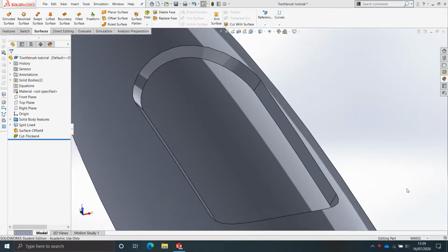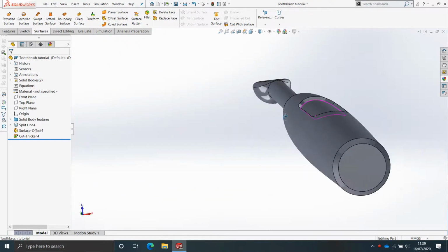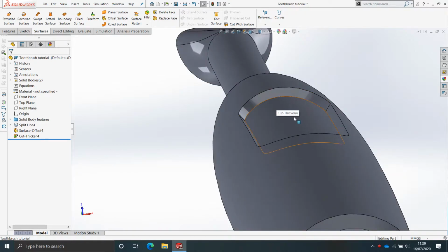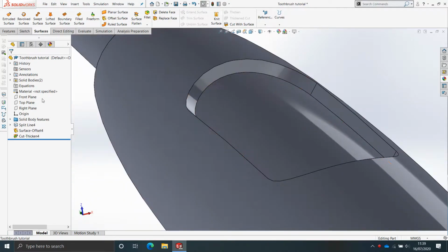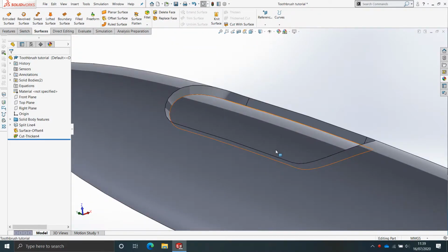So, now that we have the recess slot geometry, we can think about adding a button that will sit in this slot and that will match the curvature of this front face. And whilst we want to add a button in here, we want it to be a separate part, or a separate body in this part file, should I say. In order to do that, it's actually pretty simple, and we can just use the rollback bar.